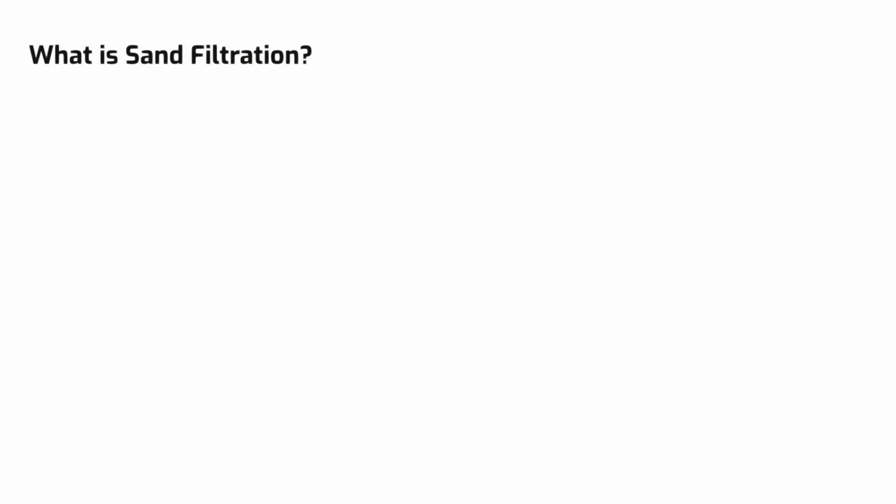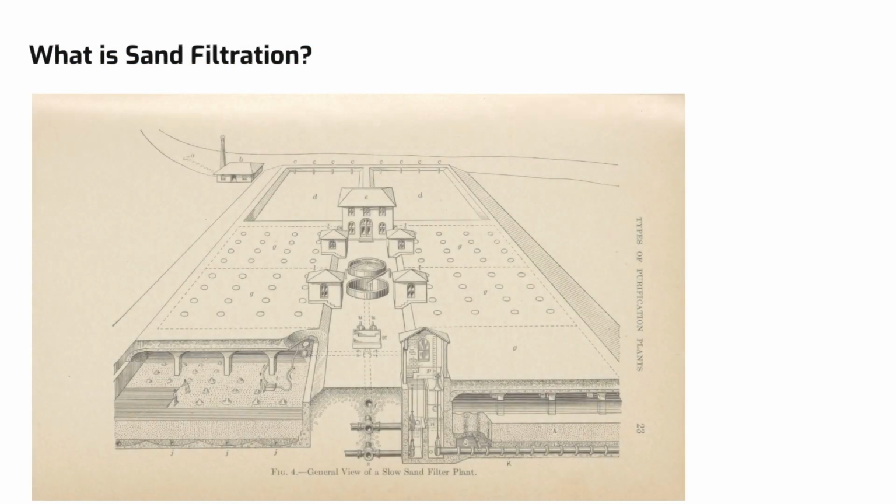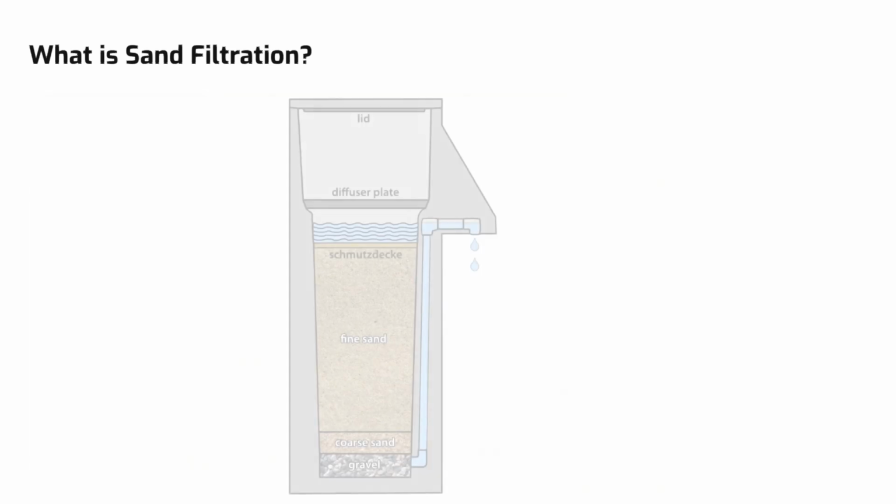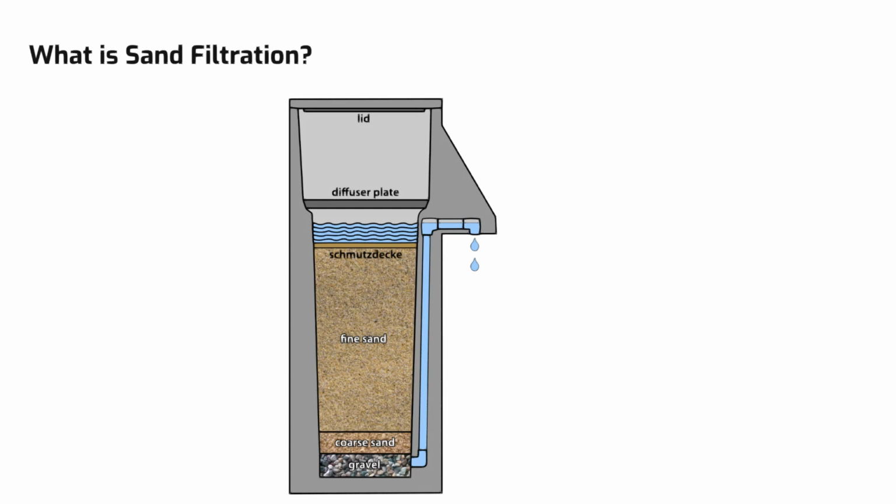Sand filtration stands as one of the oldest and most widely used water treatment processes. It involves the passage of water or wastewater through a bed of sand or other granular material, which acts as a sieve to trap and remove particles, microorganisms, organic matter, and other impurities.